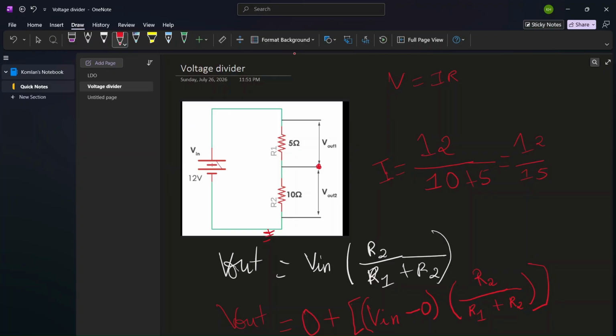And that equates to a particular current, right? So the current that's flowing through both of these resistors. That's why we have that. Because again, the voltage difference that drops across all the resistors is 12. In this case, the voltage difference is 12. Our reference is ground, that's why it's 0. But if our reference was 5, you have to make sure you put a 5 here. I'm putting 0 because I want to make sure I'm making everything visible for people.